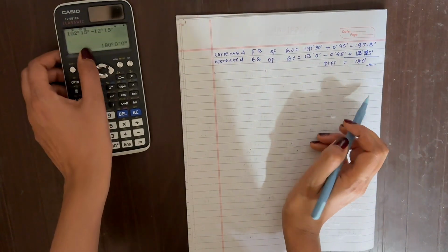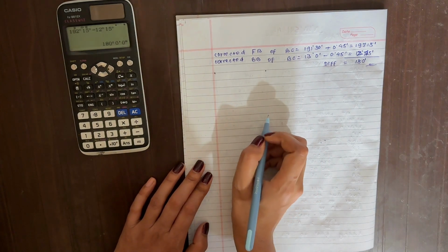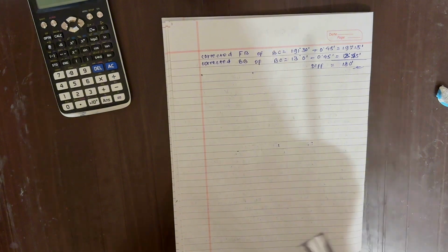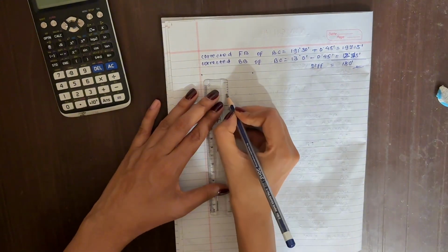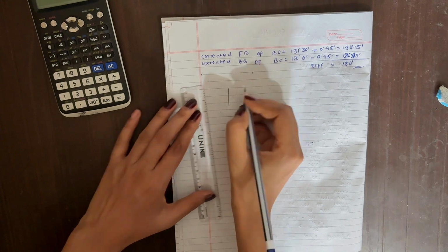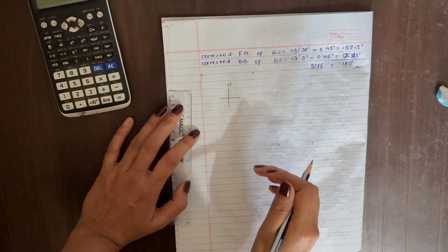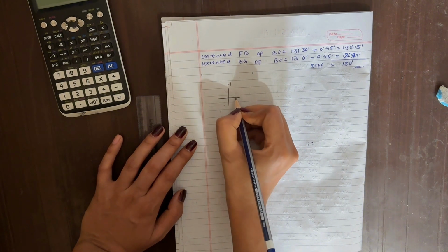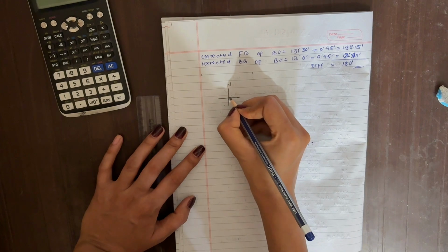Okay, so now we will draw a rough sketch of the traverse of the given lines. Let us consider this is station A, and this is north. The forebearing of AB is 69 degree 30 minute. 69 degree must lie in the first quadrant, since in the first quadrant we can measure up to 90 degree.